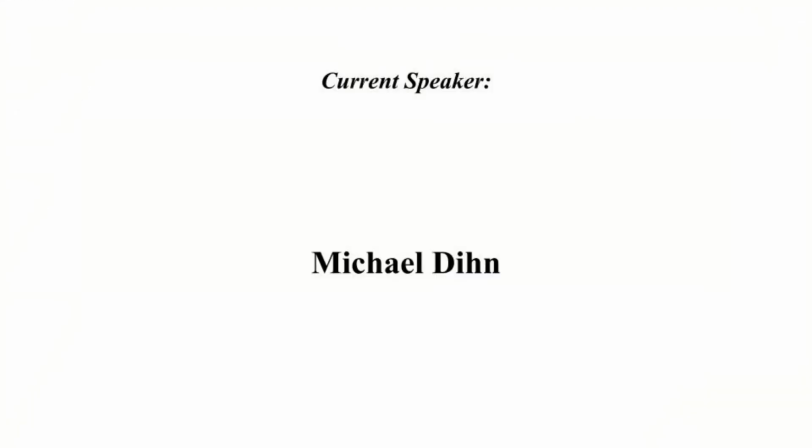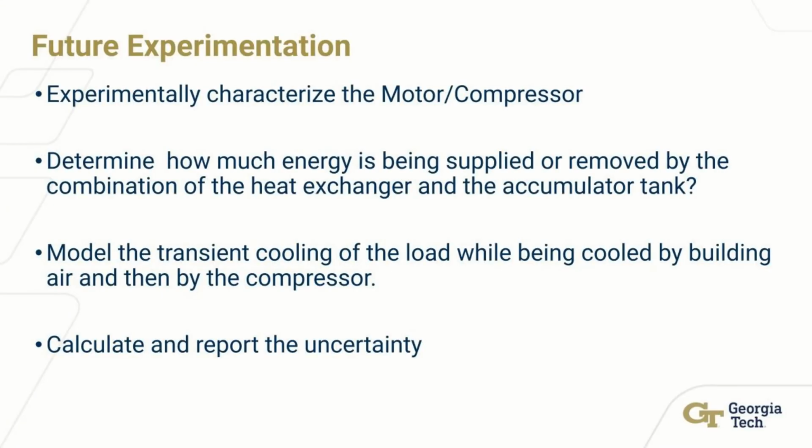refrigeration. Further experimentation utilizes a motor-driven compressor in conjunction with the vortex tube, and the relationship between motor speed and input pressure is determined at 0, 20, and 40 psi. After determining the offsets from the steady-state data collected at 0 psi, the heat exchanger and accumulator tank are examined to determine if they are necessary.